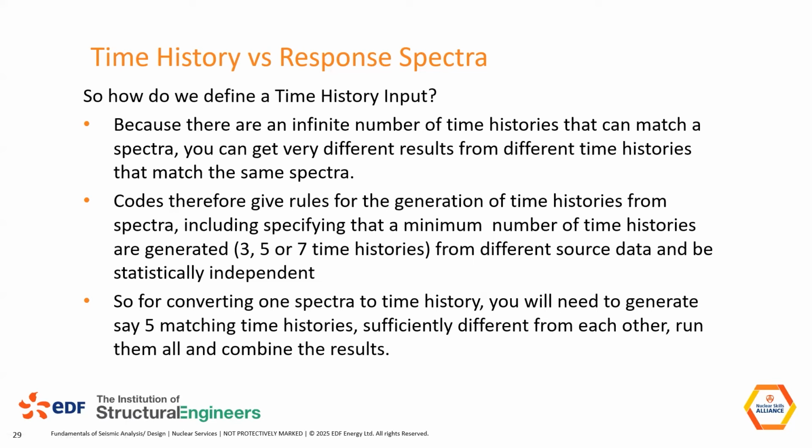You try and get a set of time histories, and remember, each time history set is three inputs, and you would run them all and then combine them at the end. Again, it depends on the code how you combine them, whether you envelope them or average them. But that's the principle of what you're doing.